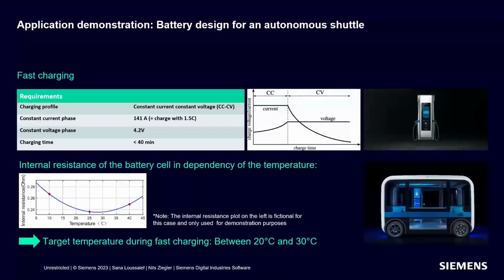In our case, we have to charge the bus in a range between 20% and 99% SOC. Then, as an additional criterion, we want to charge the cell with a minimal internal resistance to keep the generated heat of the cells during the charging as low as possible.